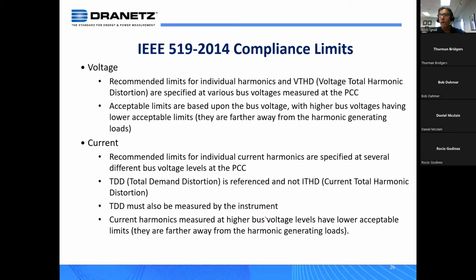And there's a very simple way to look at this. Traditionally, or even in theory, the power producers, even the coal, the gas, the nukes, produce virtually clean sine waves, okay? Even the alternative energy, PV plants, DERs, things like that, have harmonic filtering to make sure they produce fairly clean sine waves. So it's not a transmission issue. Harmonics typically don't originate in the transmission system. As I said before, they originate from the loads that we plug in: the arc furnaces, the individual loads, the computers, ranging from large to small.